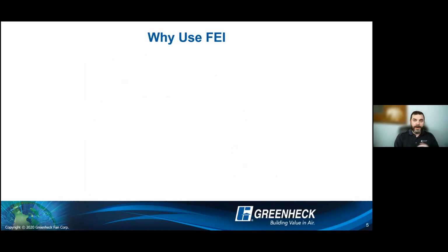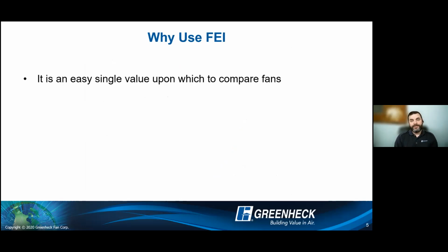So why do I use an FEI, right? The first reason to use FEIs in your fan selection process is it's just an easy way to compare one-to-one. Right now, when I look at fans and I look at different fans I can use for performance, I'm usually using items like, hey, can it meet my performance? Kind of an important one.